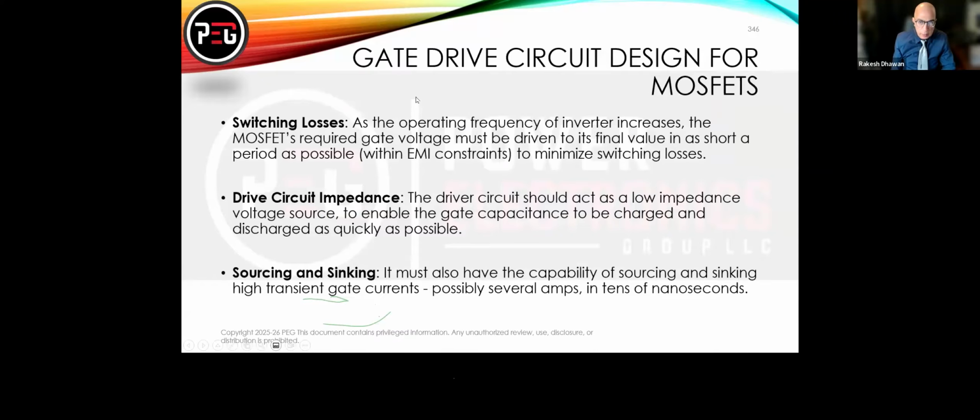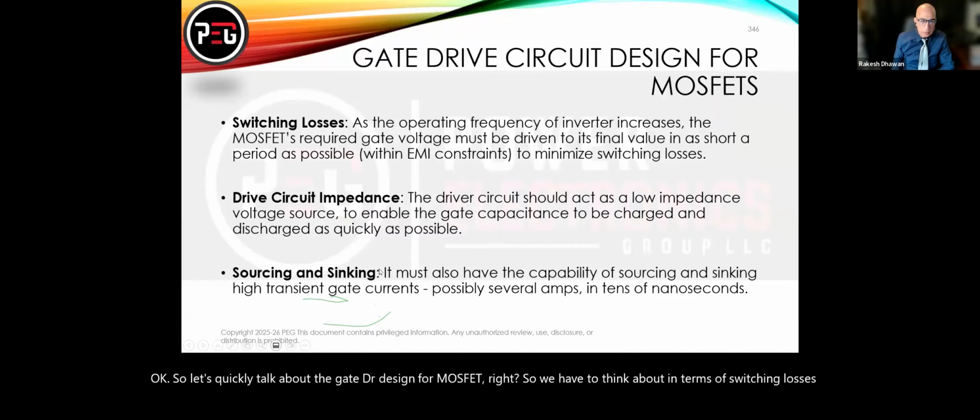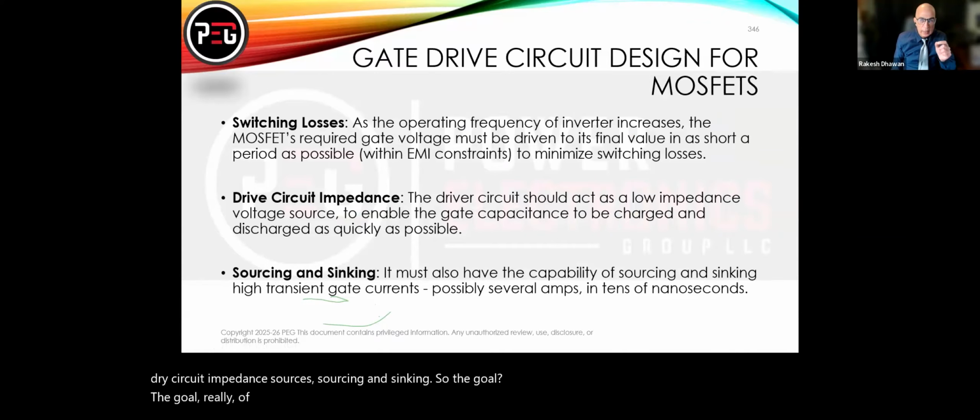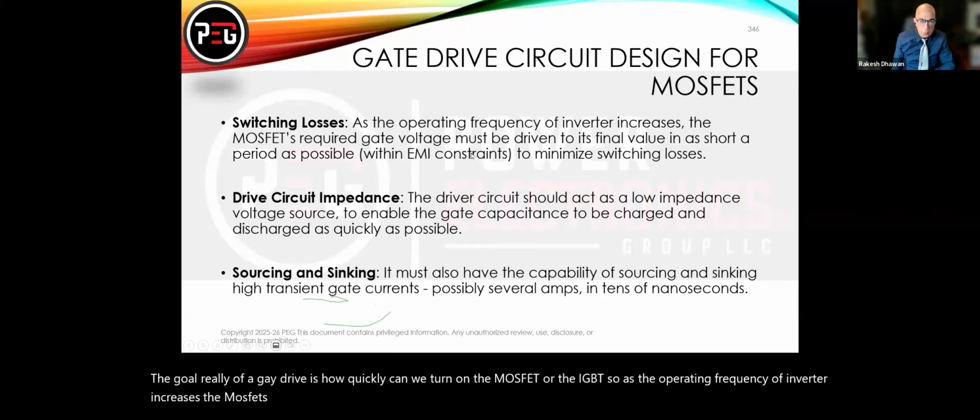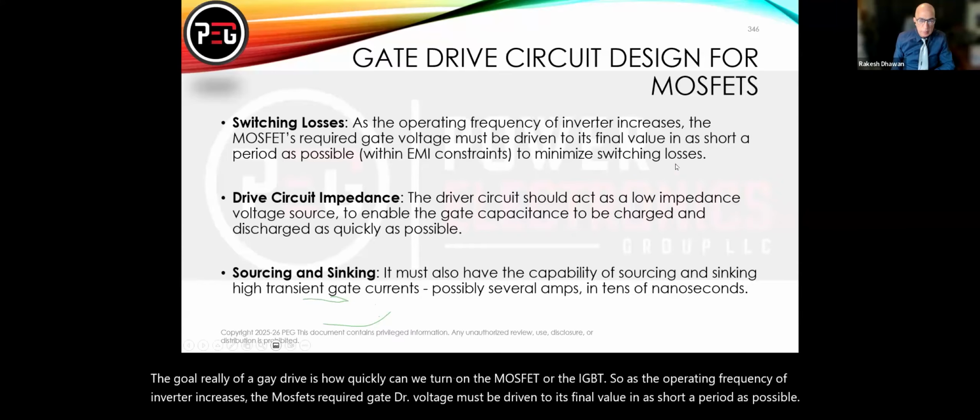Okay, so let's quickly talk about the gate drive design for MOSFETs, right? So we have to think about switching losses, drive circuit impedance, sourcing and sinking. The goal of a gate drive is how quickly can we turn on the MOSFET or the IGBT. As the operating frequency of the inverter increases, the MOSFET's required gate drive voltage must be driven to its final value in as short a period as possible within EMI constraints to minimize switching losses.